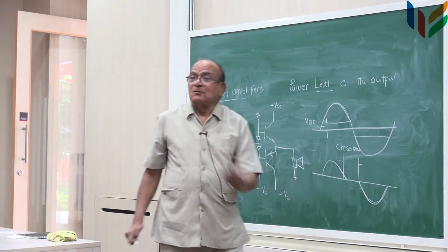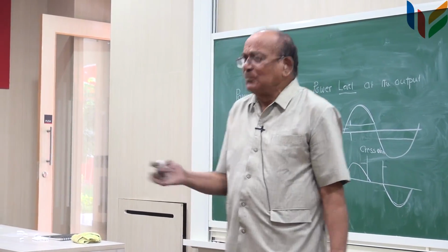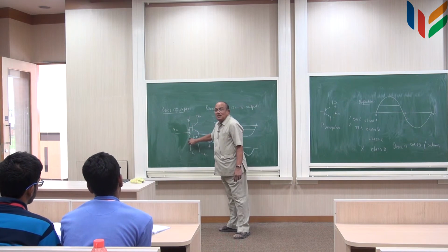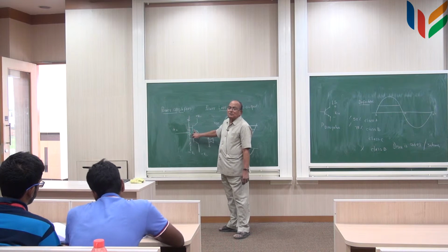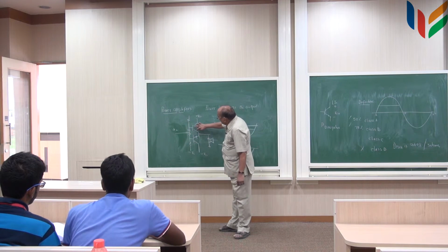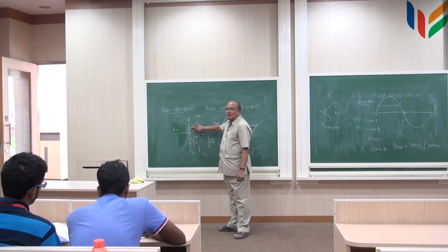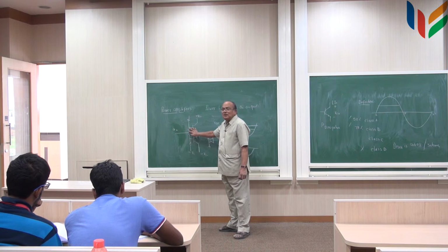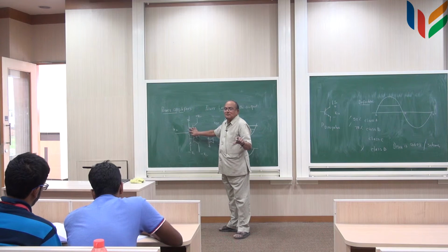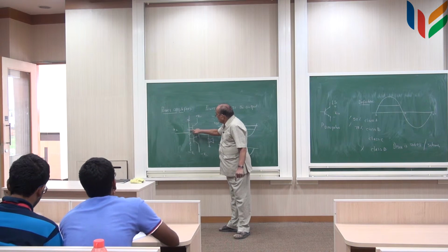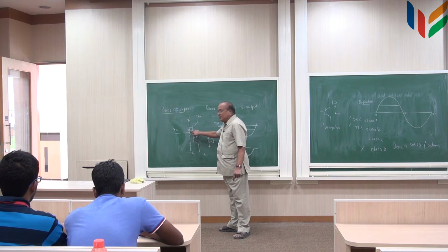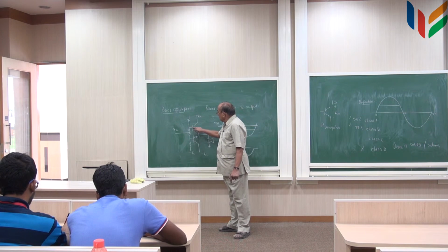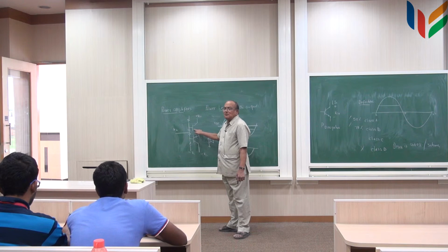You put 2 diodes, you don't have to put diodes, you can put resistors also, 2 resistors here, but the logical thing is to use diodes, because the VBE for conduction is made up by this VBE already available. So, if you now look at this loop here, this VBE is cancelled by this VBE, so both of these will be ready to conduct. Are you with me?